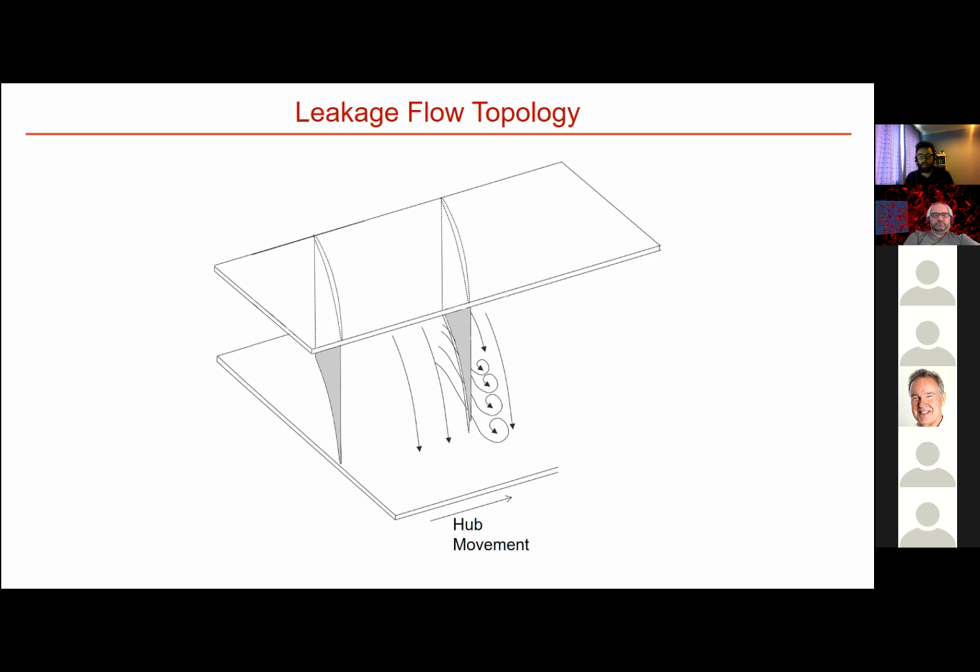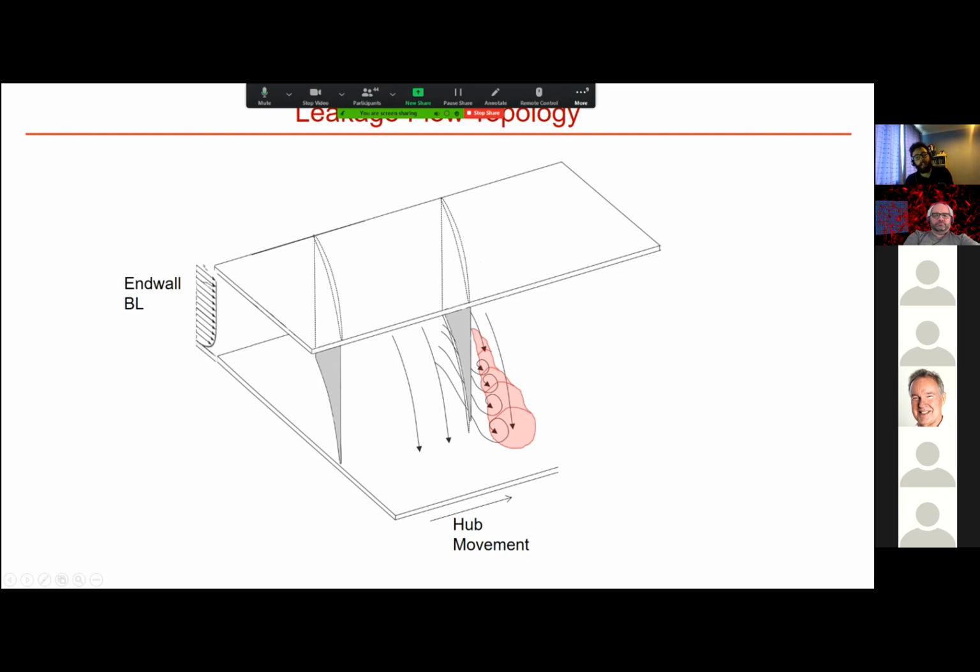Due to the different velocity magnitudes and directions of leakage flow, end wall boundary layers, and the passage flow, irreversible viscous dissipation occurs at the exit of the gap and far into the passage. This creates loss through a three-dimensional turbulent mixing process. And because of the issues accessing the geometry and complex flow topologies, experimental investigations into tip leakage flows are often difficult. Therefore, a high fidelity simulation is what's required to gain further understanding of this flow.